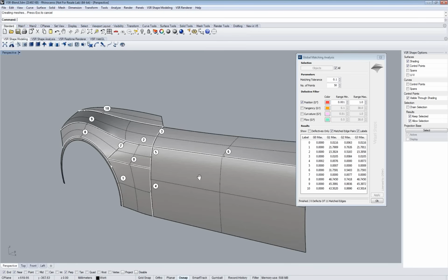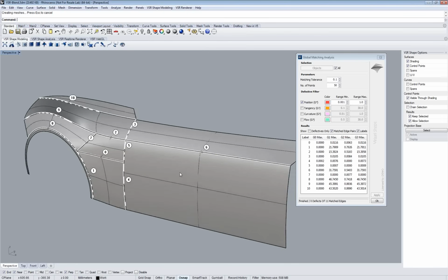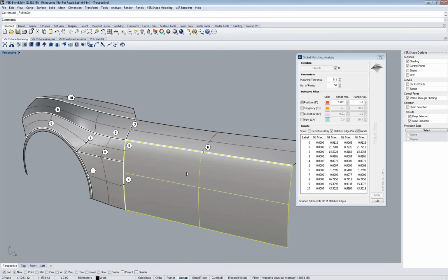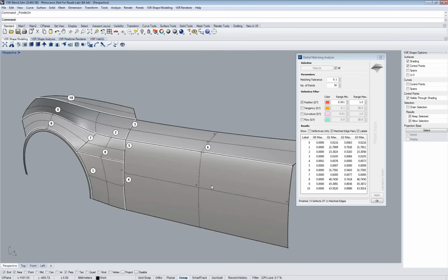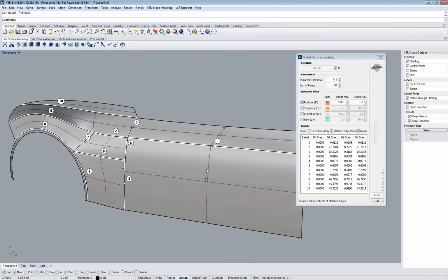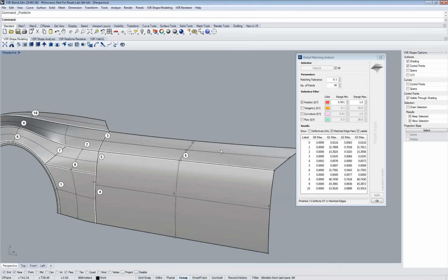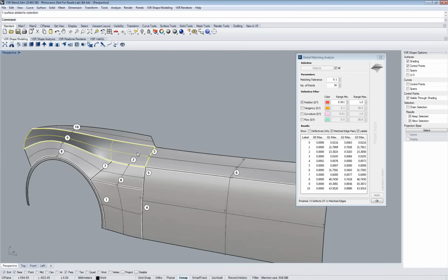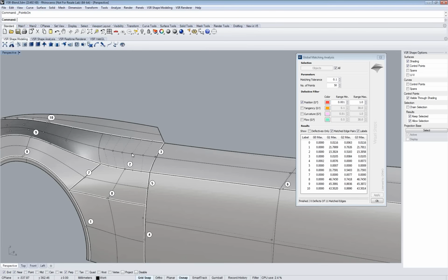Yes, it's actually a good question, and this is a general rule you've got. Taking a look at the right surfaces here, you see that they only got 3 control point rows in this direction and 3 control point rows in the other one. Having a look at the other surface here, you see we've got a lot more control points in the surface on the left, because we've matched it to the lower part here.